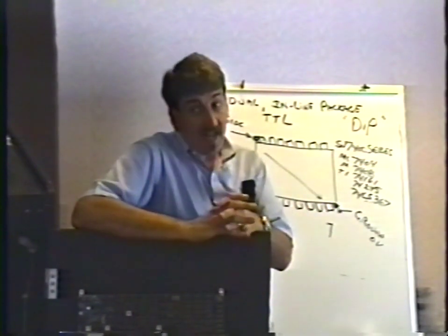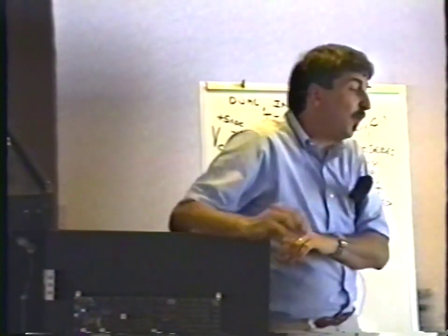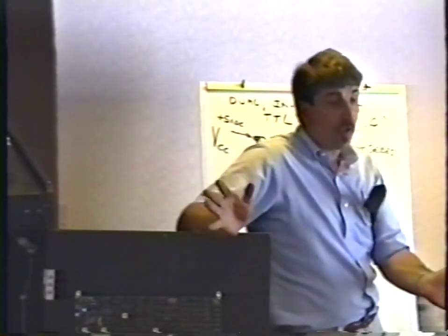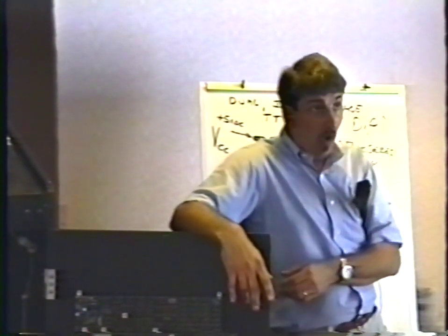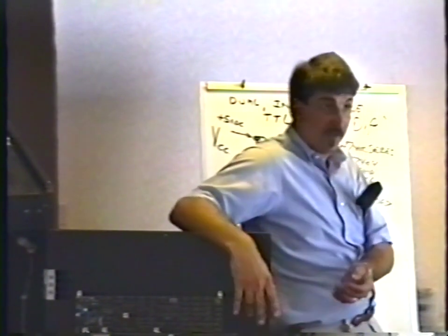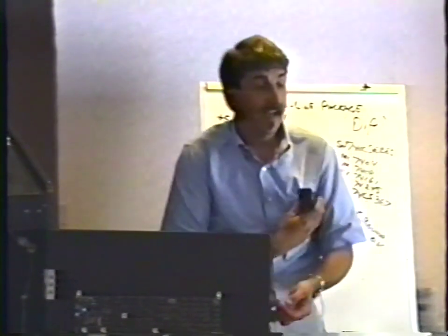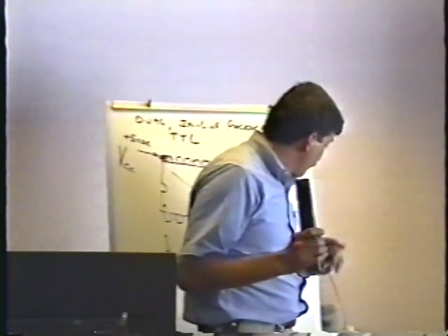Another problem that happens on boards that you can fix real easily is where the game works perfectly okay when it's cold, but when it warms up, it fails. We've all had these kinds of problems. Or it works perfectly okay when it's warm, but it doesn't work when you first plug it in, or something like that. These are thermally intermittent problems, and these are real easy to find.